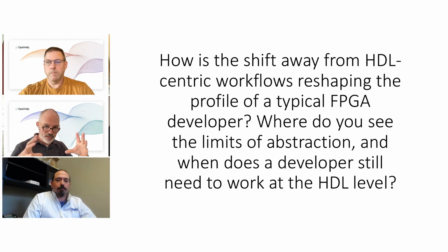So we're in the middle, and we find that with the limits of abstraction here, those types of tools aren't all that useful when you're trying to design a high bandwidth interface to an A to D converter. That typically has to be carefully designed at the hardware level, at the pin level, understanding the specifications of the device itself. So that's how I would answer this question. Jake, do you have anything else to add to that?